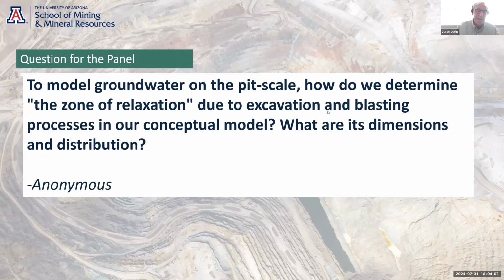Imagine a rock, if it was infinitely strong, you might be able to put a pit in that's a kilometer deep and not see much relaxation at all, because maybe there's very, very few fractures in it compared to something which is much weaker and much more jointed. It's going to show a larger zone of relaxation. And the orientation of the joints. Yeah, all that. If the joint orientation is parallel to the slope, you're going to get more.